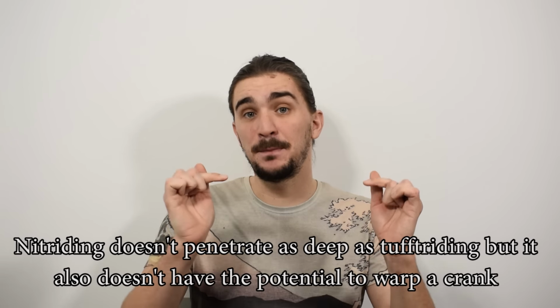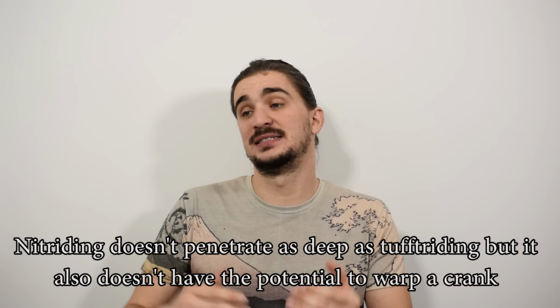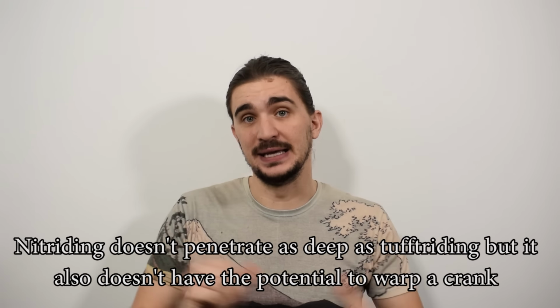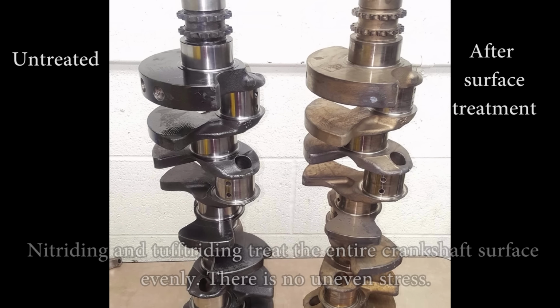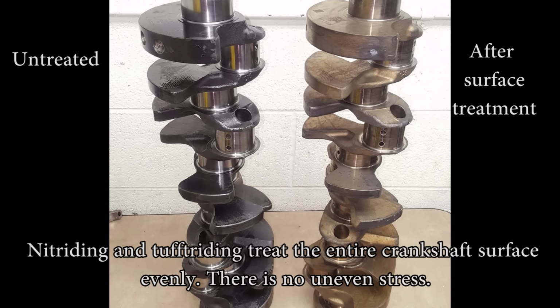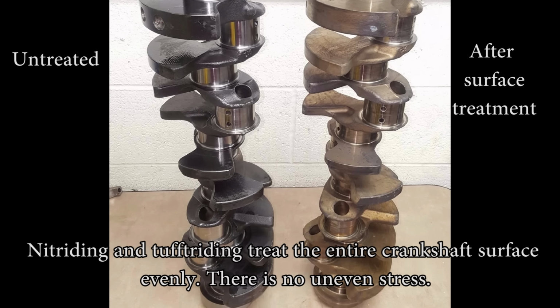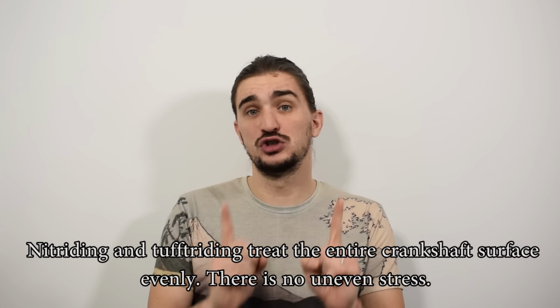Nitriding doesn't penetrate as deep as tuftriding, but it does have the advantage in the sense that it doesn't introduce any warping to the crankshaft. Unlike induction hardening, both tuftriding and nitriding harden the entire surface of the crankshaft evenly, so there aren't any uneven stresses left behind, and this makes these processes more suitable to the forces seen in extreme racing applications.